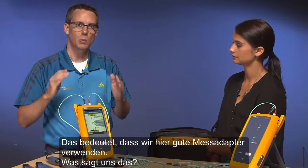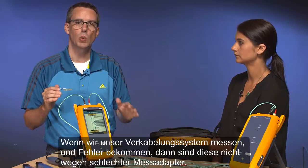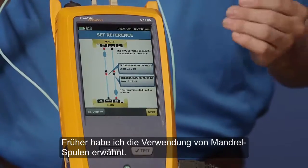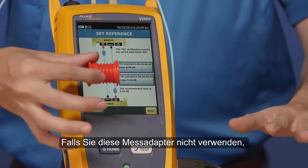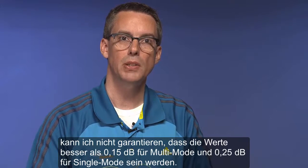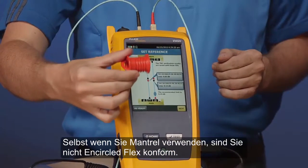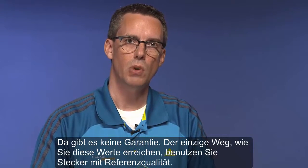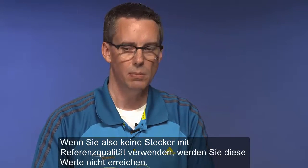So what that tells us now is when we start making measurements on our cabling system, if we start seeing failures, it's not because of poor test reference cords. It's because there's something wrong with that cabling system. Now previously I mentioned the use of a mandrel here. If you were not to use these test reference cords, I cannot guarantee that you're going to get better than 0.15 dB for multi-mode and better than 0.25 dB for single mode. Even if you use a mandrel, you're still not going to be compliant. There's no guarantee. So the only way that you're going to hit these numbers is using reference grade connectors. If you're not using reference grade connectors, you're just not going to hit these numbers.